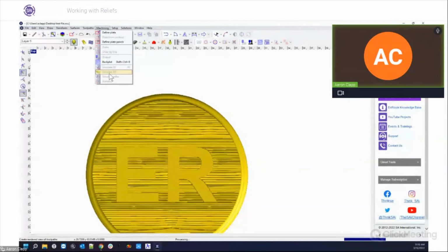So let's say you've got this 1/4-inch ball nose, and the only other one that you have is a 1/8-inch ball nose. Obviously that 1/8 is going to take a long time, but you're curious to see what the difference would be between an 1/8 and a 1/4-inch ball mill. Well, you could toolpath it with the 1/8, process it with a simulate 3D, see how it looks, and then try it with the 1/4-inch ball nose and see how it looks. If you think it looks pretty decent and you haven't lost a lot of quality or detail, I would go with the larger bit.